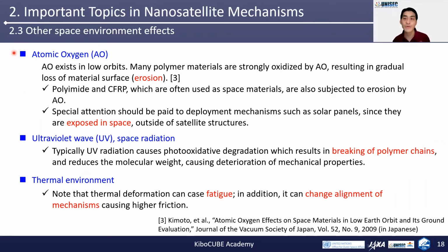This is called erosion. Polyimide and carbon fiber reinforced plastic, which are often used as space materials, are also subjected to erosion by AO. Special attention should be paid to deployment mechanisms such as solar panels. They are exposed in space outside of satellite structures, so please be careful for its lifetime.